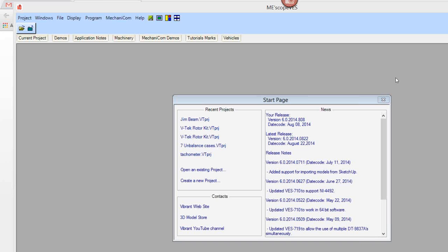Now, the most common way of taking data is with an impact hammer and an accelerometer. There we measure the acceleration response divided by the impact force. And that type of measurement, the FRF, isolates the modes of vibration in that data. It's a frequency response function. It's a frequency spectrum, and the peaks in that spectrum are evidence of modes of vibration. So that's a normal way we do modal.